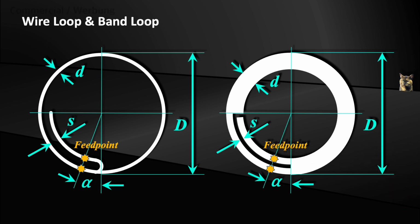Based on the frequency and the diameter d of the conductors, all other parameters shown here can be calculated. I will demonstrate the tool using a new example. It's about dimensioning a loop antenna for the 2.4 GHz band, namely for the copper wire solution and the foil or printed circuit solution. In a later video, I will show the realization and then analyze the antennas with a vector network analyzer.